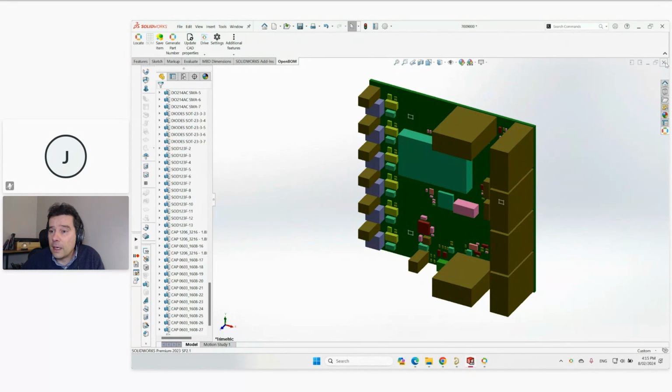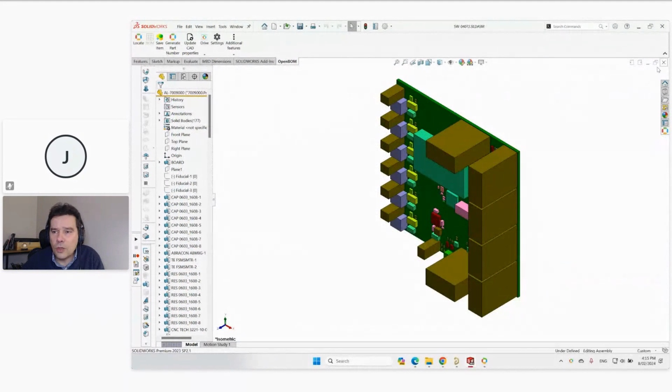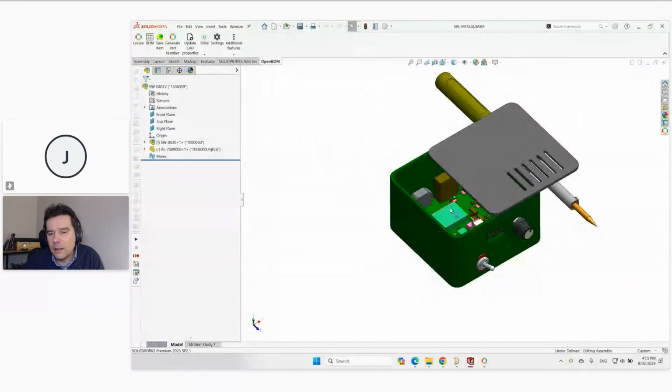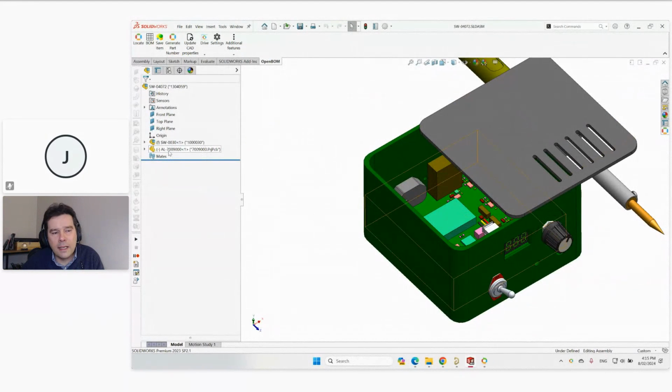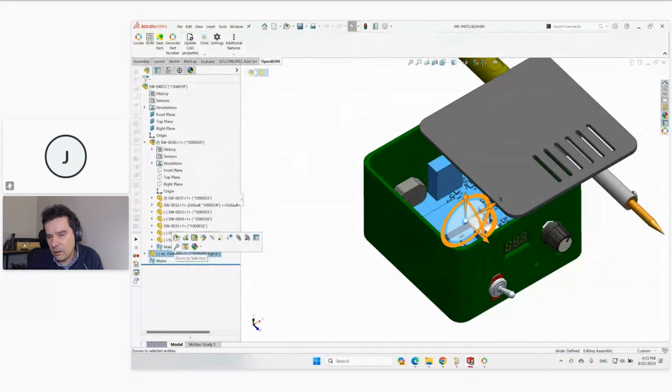So don't use the Parasolid. Go for IDF, and also some other recommendations on how you structure your bill of materials when combining ECAD and MCAD. You don't need to put everything where it actually lives. Like this PCB is inside this assembly, but you actually don't need to put it precisely where it lives. Sometimes it's good to separate ECAD and MCAD into different structures so you can manage collaboration better between different teams. So they are not so deeply together.